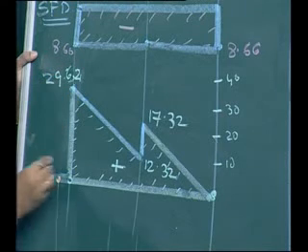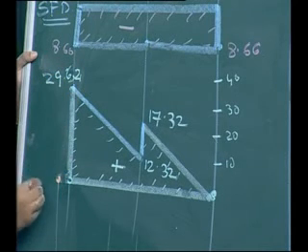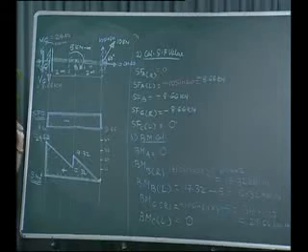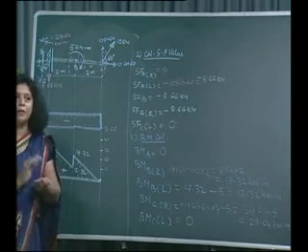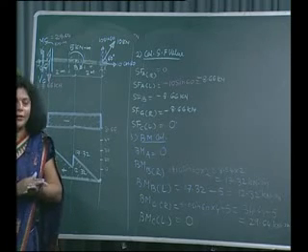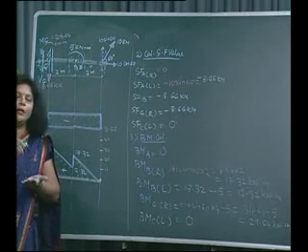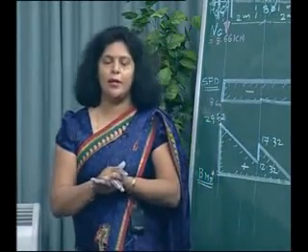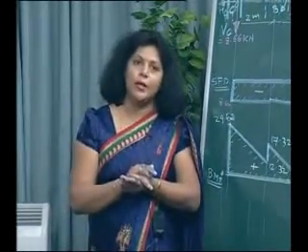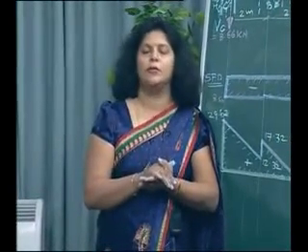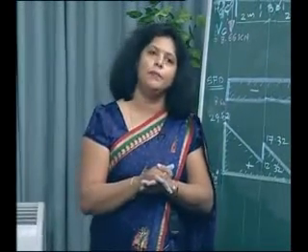Okay, we have covered all types of problems, so you will be able to solve any numerical if your basic concept is clear. The basic concept is: what is the type of loading? Depending upon the loading, you have to draw the diagram. If it is a point load, vertical line in shear force. If it is a UDL, inclined line in the shear force, and a curve of second degree in the bending moment.